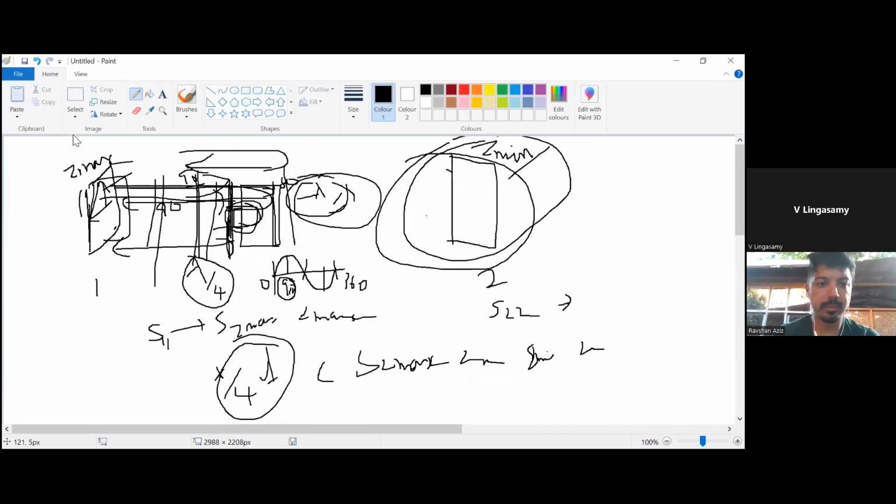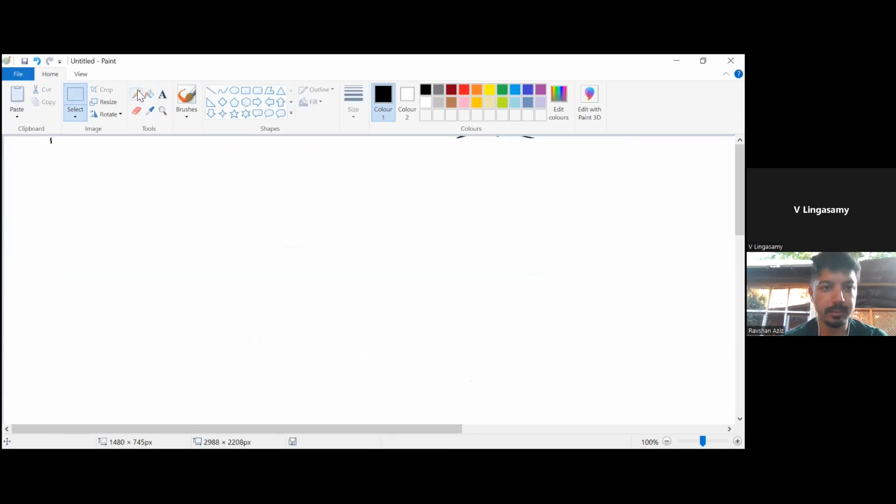So now the last point is, see, you have a unit cell like this. Then you have a ground plane or reflector. Then you have the patch. Just now I told you that you are going to have a broadside direction. For example, the plane wave is going to come over here and get reflected over here. This is one case. The same unit cell will give you different phase shifts when the angle of incidence is like this.